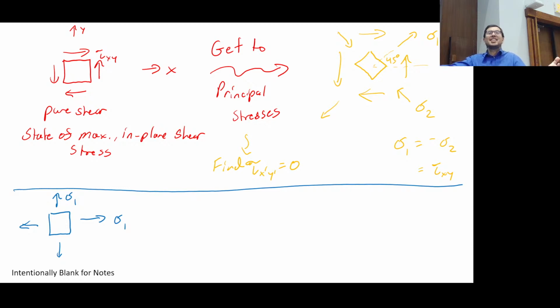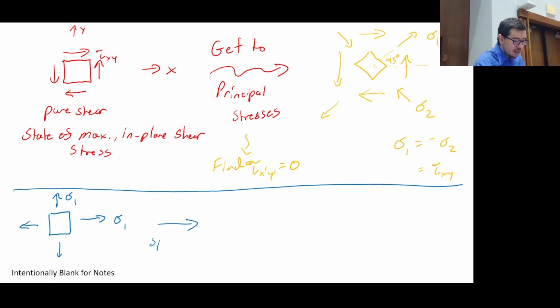Take a guess. The two types being spherical and cylindrical. Yes, even if you didn't know anything, you'd say that thing is completely symmetric, right? So yes, this would be the state of stress in a spherical pressure vessel, where sigma 1 and sigma 2 are PR over 2T.